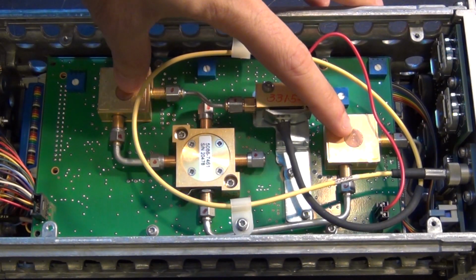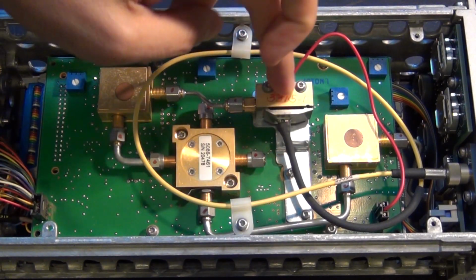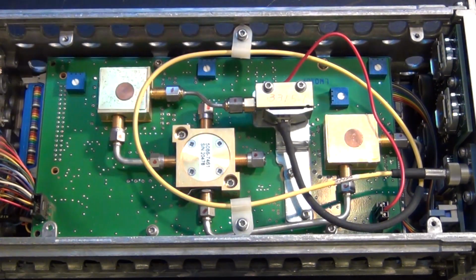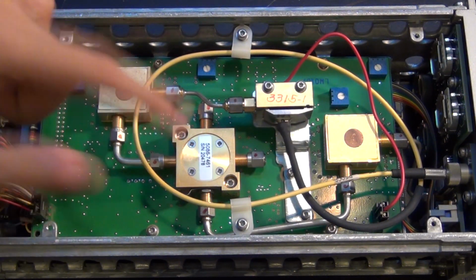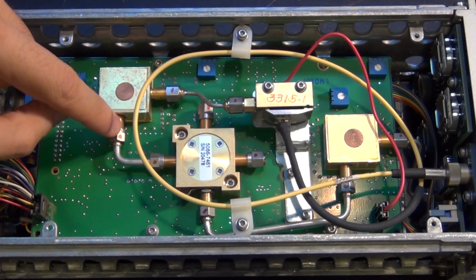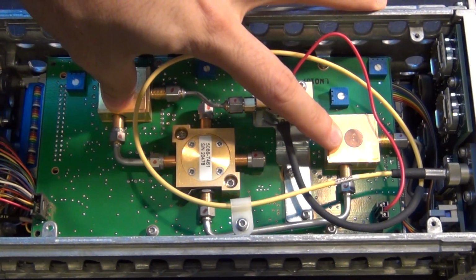Same thing with these. These are almost identical, not quite the same, because the input dynamic range between the photodetector and the electrical input are not the same. That's why these are not identical modules. So what is this then? Well, we just talked about it. This is the impulse generator, the pulse-shaped impulse generator that goes into the two samplers.